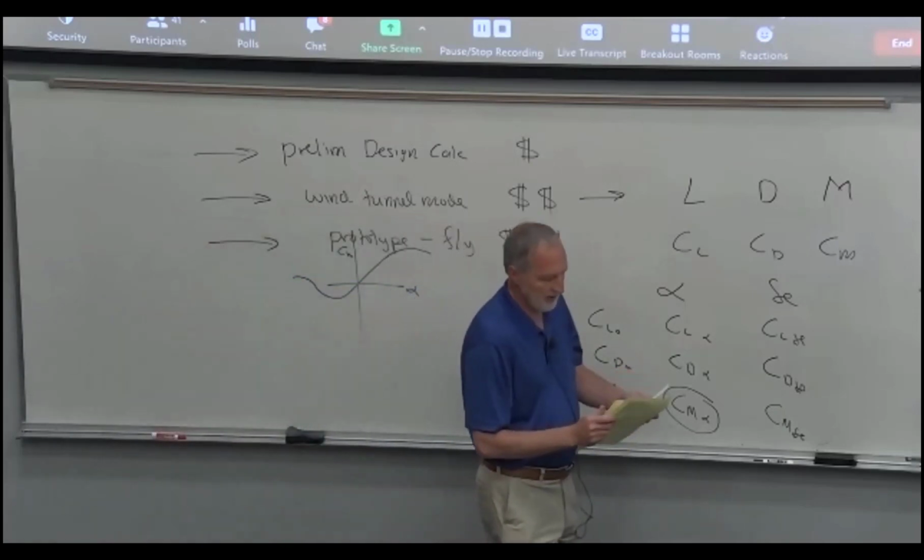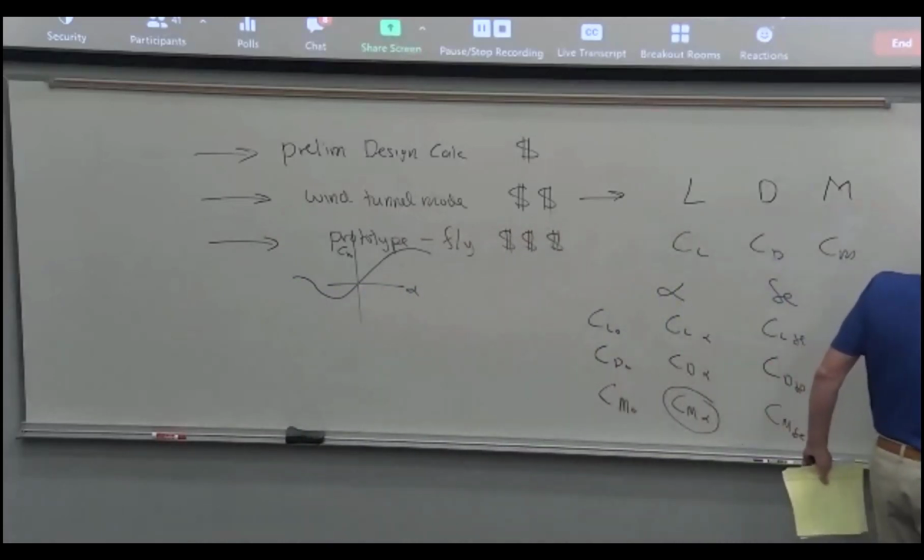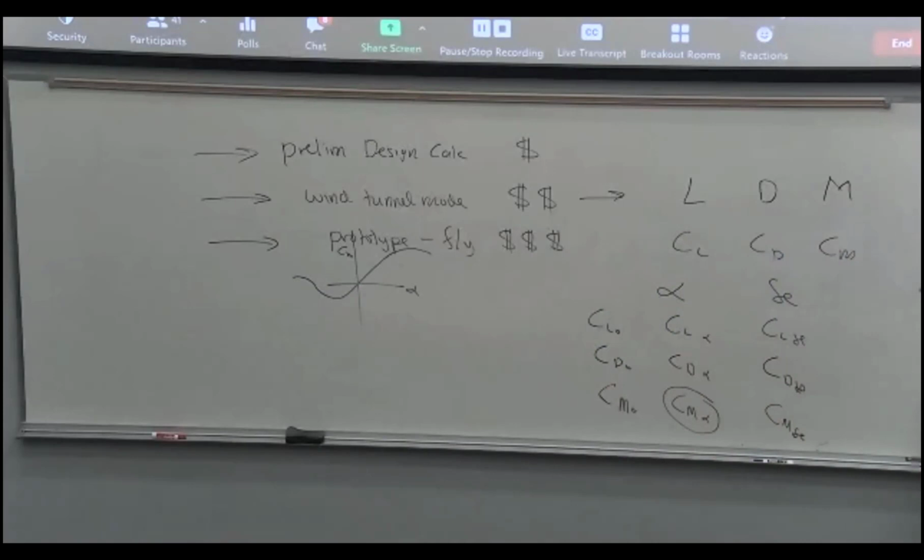And then you do the same thing for lateral directional, right? We want to be able to predict rolling moment, yawing moment, and side force. And so you can measure those values versus beta, rudder, and aileron so that you can get all of the derivatives that go into that model. So I'm going to measure CY, side force, rolling moment, and yawing moment versus a beta sweep.